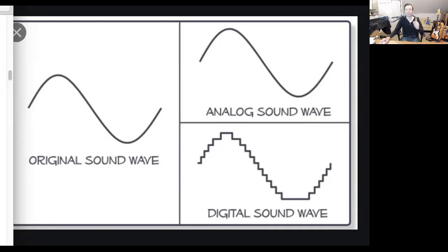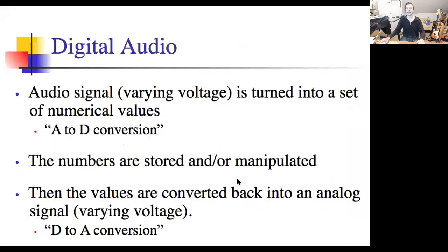What is important about that is that we need to have some standards, right? If you have a computer expecting a certain number of samples per second and you read it back at a different rate, it will actually change the pitch of the audio. Maybe you've experienced this in a DAW. So the standard for audio on a CD is 44.1 kilohertz, or 44,100 times a second that we sample the incoming audio, or that we record a value of the voltage.